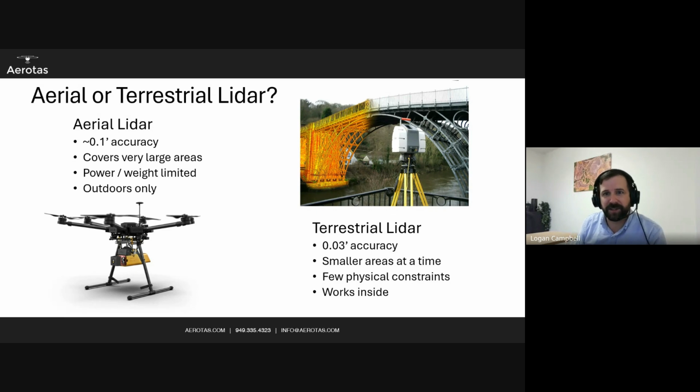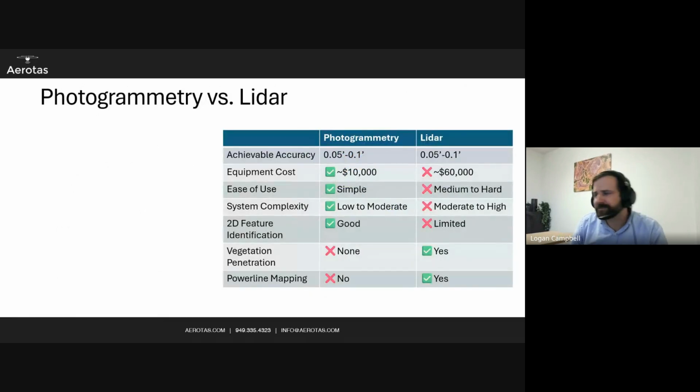There's that word again that I'm going to use a lot. Balance things like the power of the laser, the battery, the distance that it can cover. They're just different needs. So we generally discourage people trying to buy a jack of all trades LiDAR sensor, strap it to a drone here, a car there, an ATV, a backpack, and then put it on a tripod. It usually winds up being a pretty clunky solution overall, but we'll talk about hardware in just a little bit.